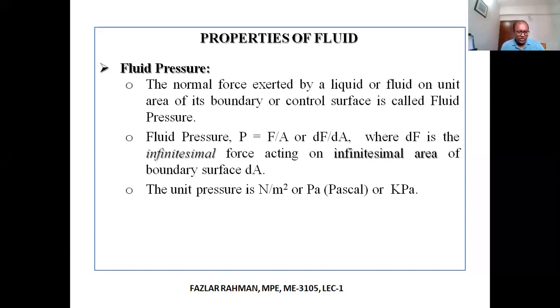For example, you are working at a refinery and you have a pipeline system, and there is a pump that should run for 20 years, but it breaks down after 10 years. Then what will be your investigation? You should look at whether there is cavitation in the system. If you look in the pump impeller, or if you have a turbine, look in the turbine blade. Is there any pit hole? That means there is cavitation. And what will be the effect of cavitation? Not only does the service life reduce, the performance of your pump or turbine blade, or you can say efficiency, will be reduced. Okay.